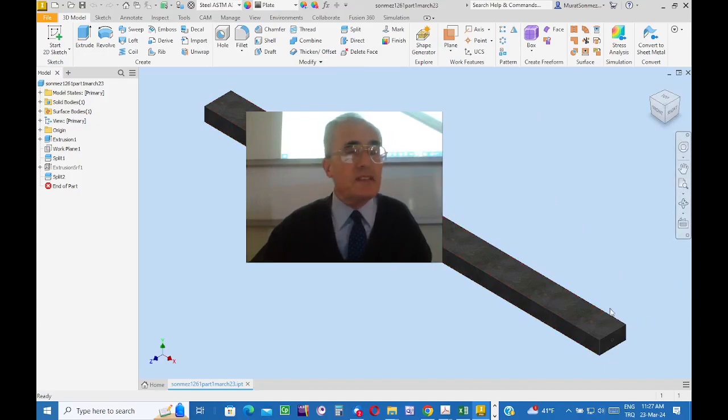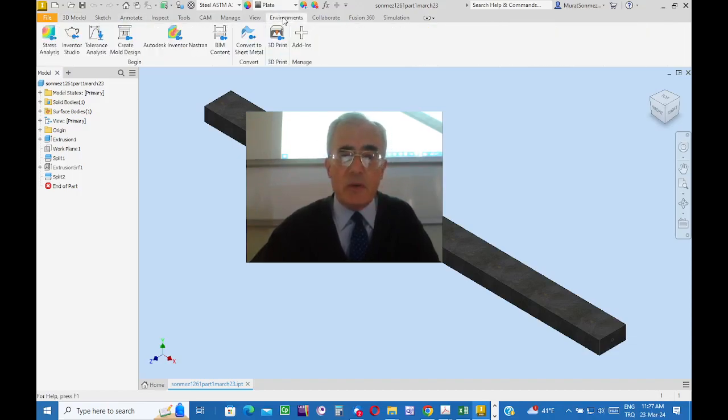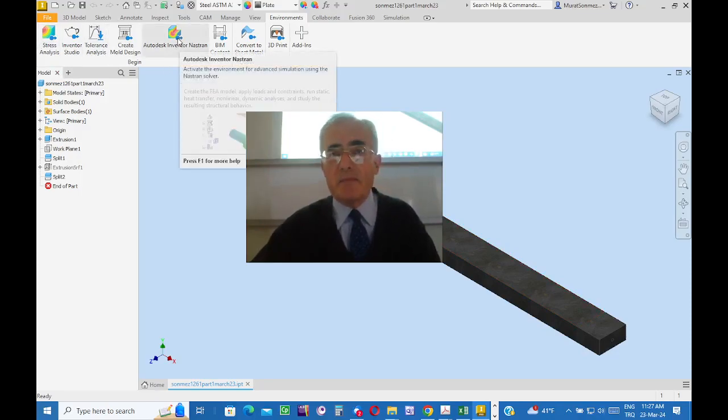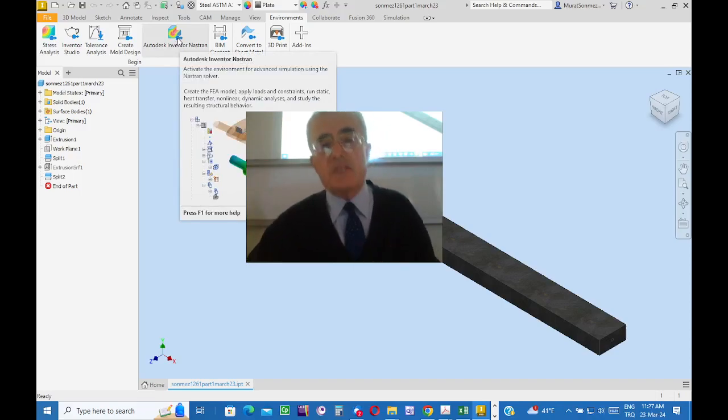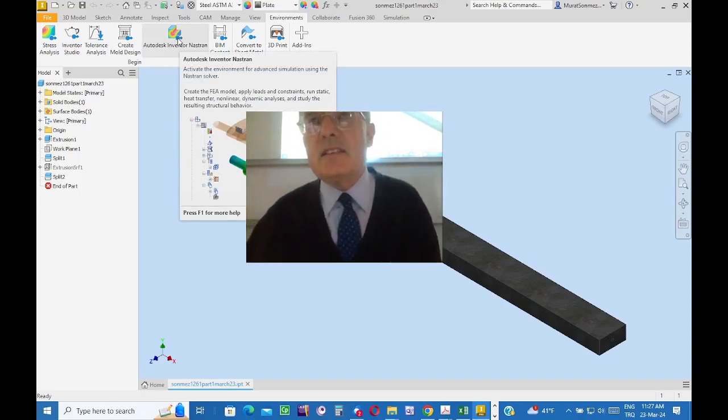First point force, and then, well, one more time. Using the same model, we are going to study two different examples. Okay, click on the environment step. Well, since Nastran is more complex because it is more powerful, you can use this software not only for linear analysis but non-linear as well. Heat transfer phenomena, study on impact mechanics, buckling, okay, thermal stress, etc., some others.